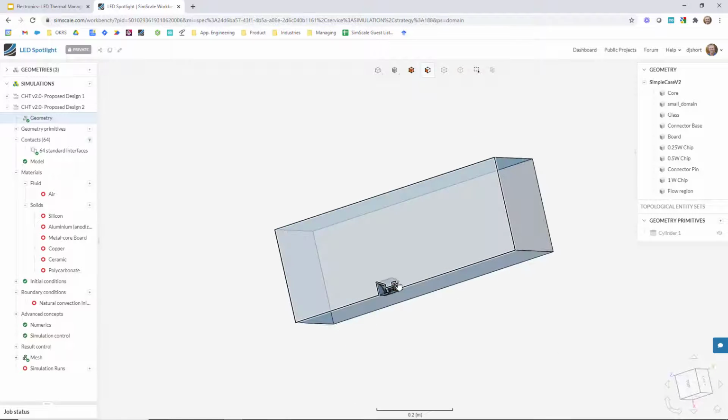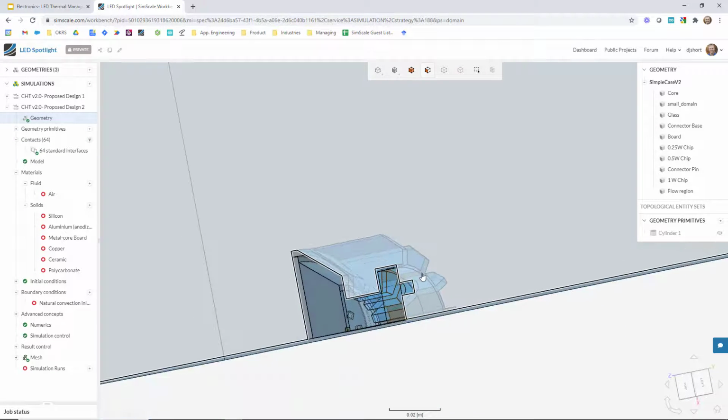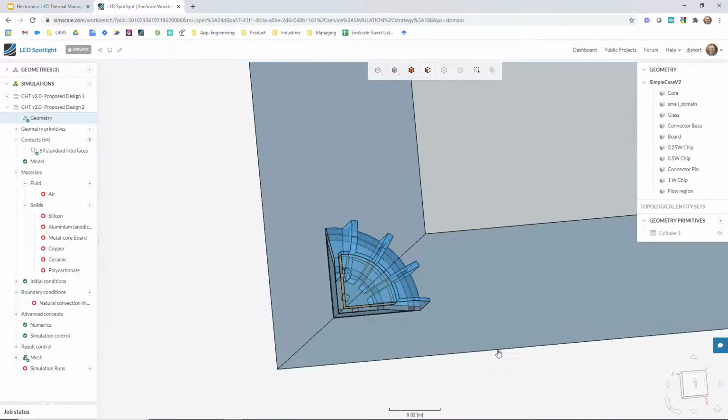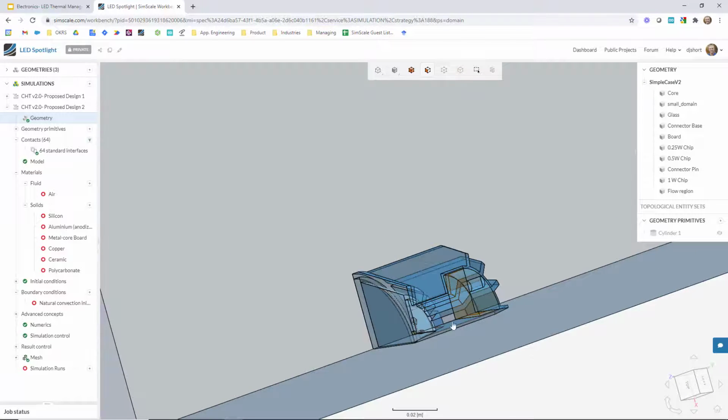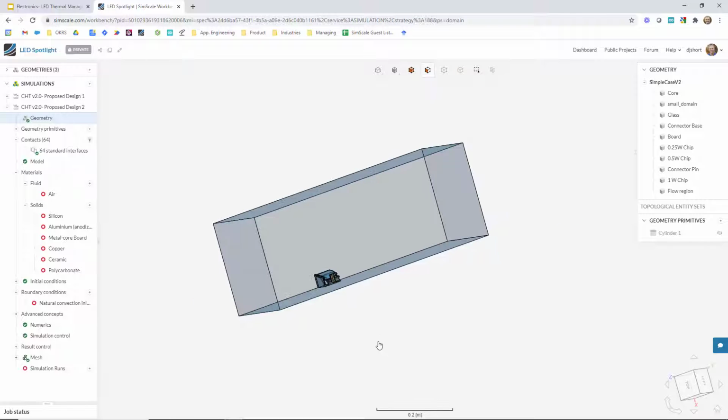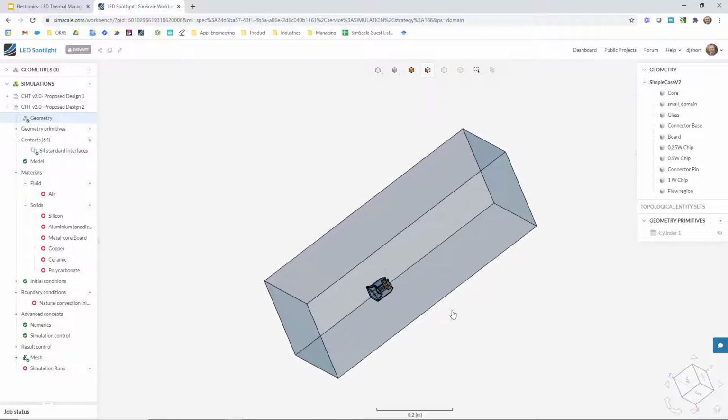And we can see that we've got some bulkier heatsink fins with a larger spacing as well. When we assigned the new geometry, what it firstly did is automatically find the interfaces between both the solid parts and also between the solids and the fluid regions. So that's done automatically for you, and we just need to worry about the actual design parameters.